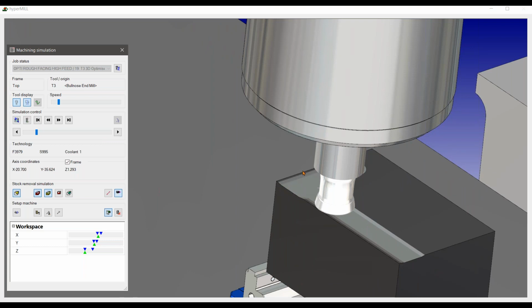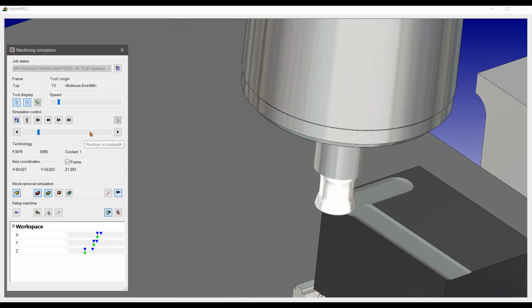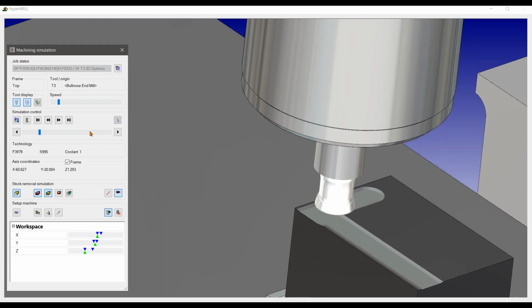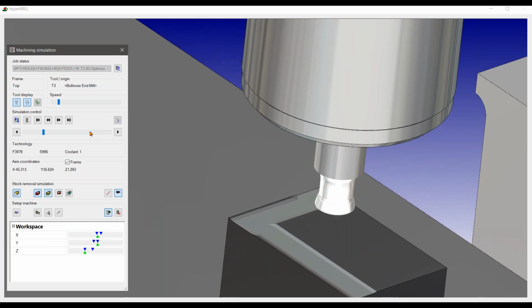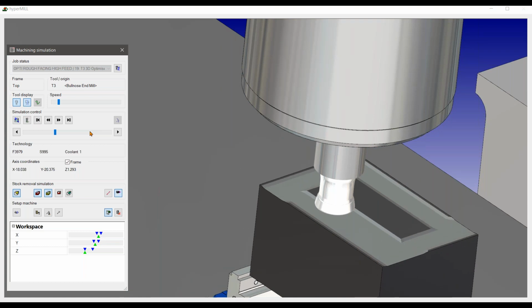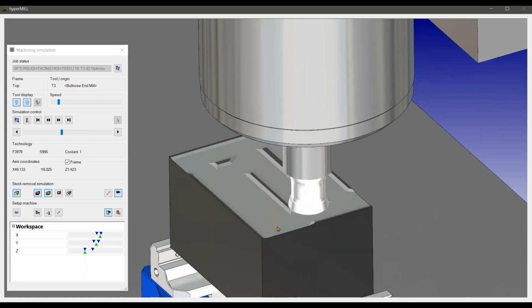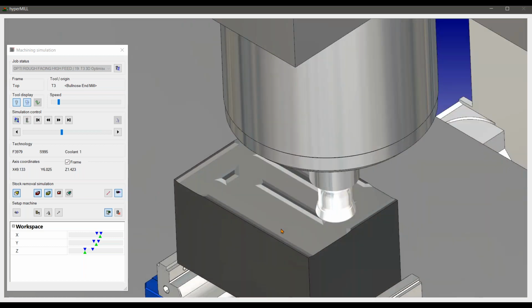If you were to simply roll around that edge, we would have a big triangular section of material. That spike is removing it. Not only that, it is also ensuring that when we're doing the arc move and changing direction, cutting is maintained on the right-hand side of the tool, and it does it per corner. Now, what you're going to witness is what we call a cusp height left behind. So we can see this material left behind.